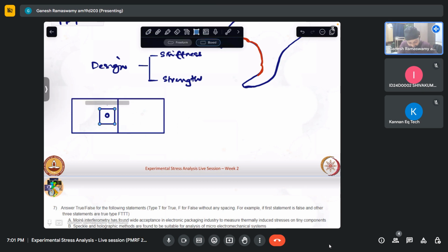There are techniques like that with which you can actually find out residual stresses. In fact, if you go to the website of Vishay Micro-Measurements, there is an entire setup of reflection polariscope along with photo stress coatings and this hole drilling method, and you will find the specifications. So those are essentially to find residual stresses that come about.